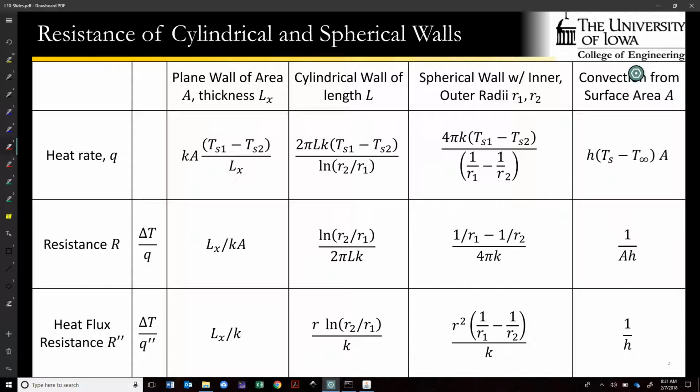So using the values in this table, it's really easy. If you have one wall next to another, and convection on both sides, for example, you just look up the values in here, paste them all together to come up with a composite total resistance, and then use this equation or this equation to figure out Q if you know the temperature jump, or the temperature jump if you know Q. That's the case in one of the homework problems on homework 3.